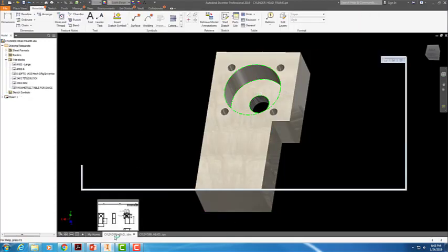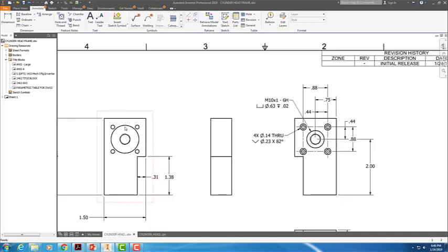So I'm going to go back to cylinder head, and there's my flat bottom hole. So it is concentric with this hole. We don't need another dimension on this. That's a weird thing that plus minus tolerancing does. So how do we know what the tolerance of this is to the axis of this hole? There is nothing in plus minus tolerancing that does that. So we're going to go to GD&T and we're going to see how to do that.